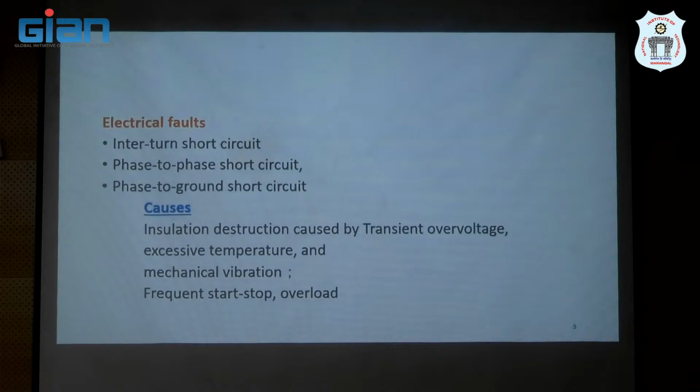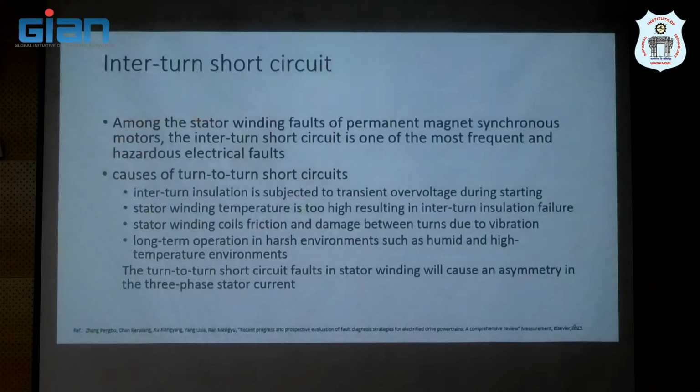And mechanical vibrations, and even frequently starting and stopping the machines, may also cause this type of problem, as do overload aspects. If you observe the interturn short circuit, usually in permanent magnet synchronous motors this type of fault is regularly observed.